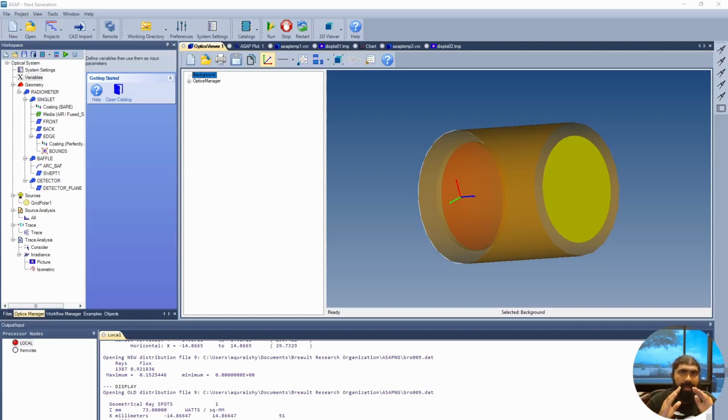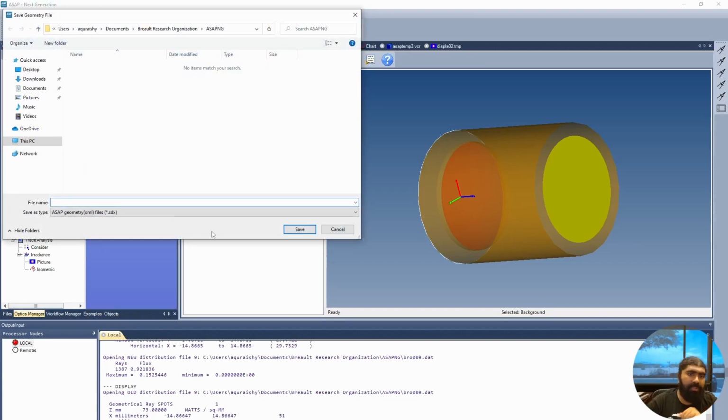Hey, Amr here. A really quick note that I forgot to add in my initial recording is you'll see this workspace right here. One of the really important nuances on this is where you save your system, because it's not by going to File, Save. You'll notice here that there are no save options. They're not available. If you want to save your optical geometry build, you have to go here and press the save button in the workspace. My apologies for not hitting this earlier, and hopefully this quick interlude will help you guys later.